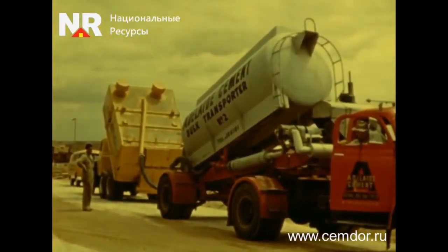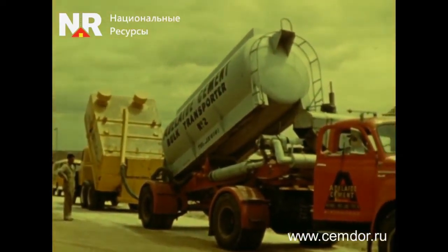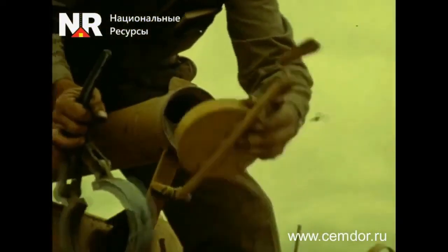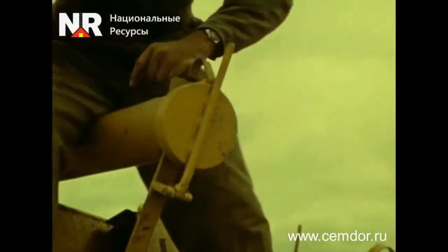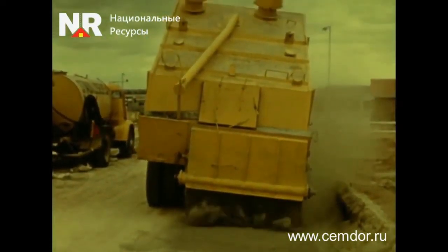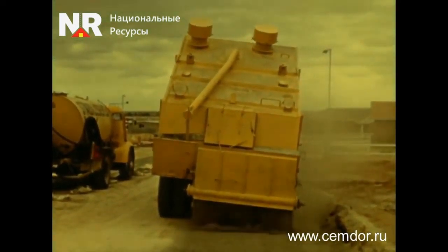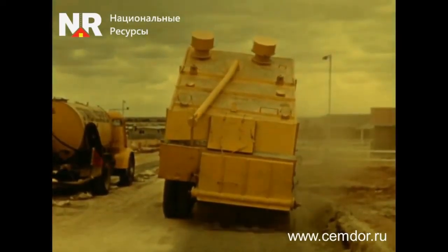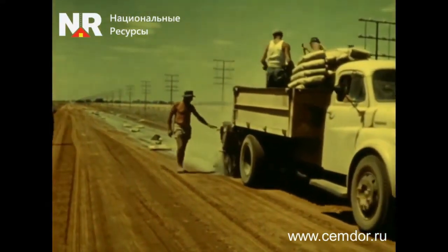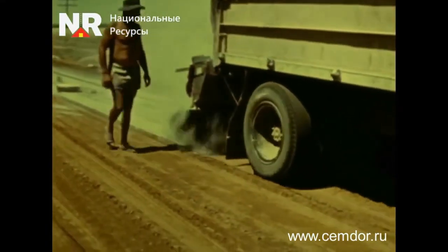Cement distribution can be carried out using a cement truck in combination with a mechanical spreader. The cement is fed from the cement truck into the spreading machine. As it moves along the roadbed, the cement spreader applies the cement in an even layer. Bags of cement can also be distributed mechanically, using any other mechanism suitable for this purpose. Thus, spreading the cement significantly speeds up the process and minimizes the impact of bad weather.